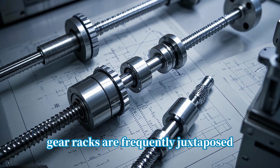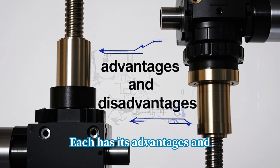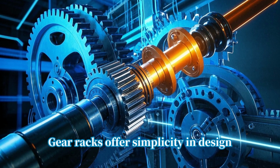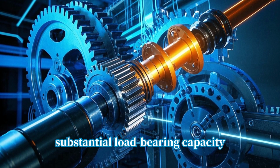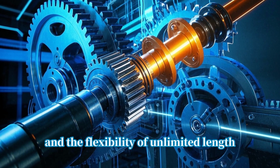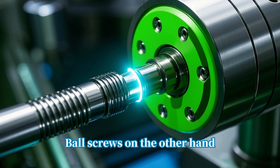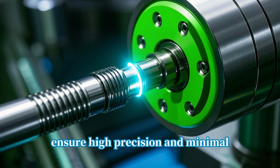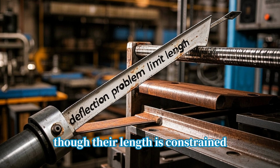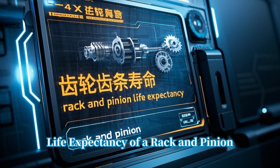Gear racks are frequently juxtaposed with ball screws. Each has its advantages and disadvantages. Gear racks offer simplicity in design, substantial load-bearing capacity, and the flexibility of unlimited length. However, backlash is a drawback. Ball screws, on the other hand, ensure high precision and minimal backlash, though their length is constrained by deflection concerns.